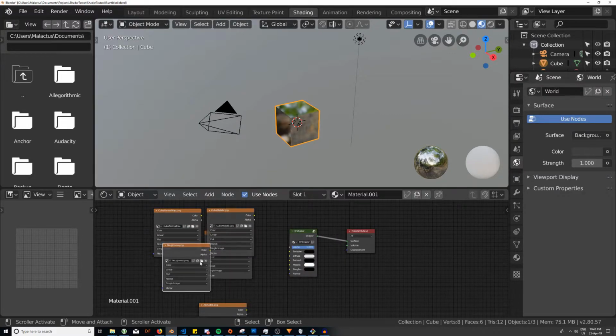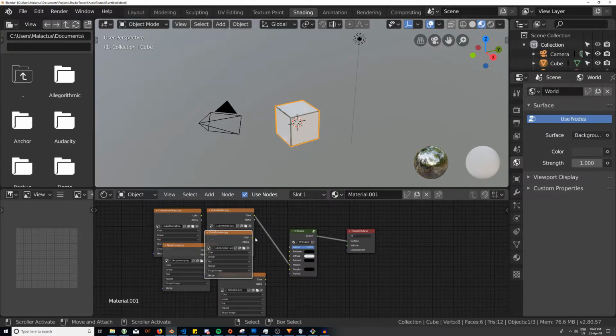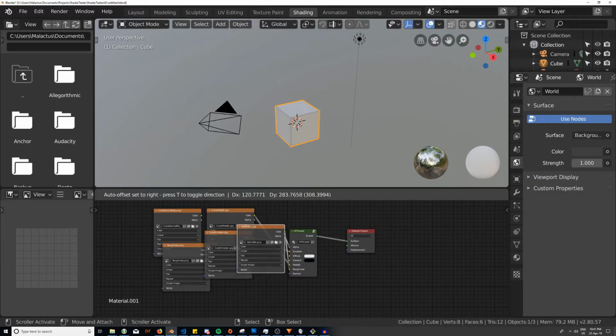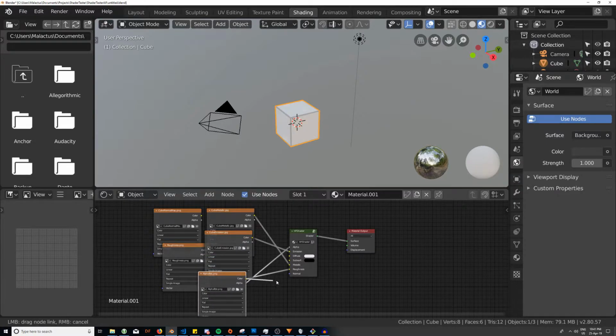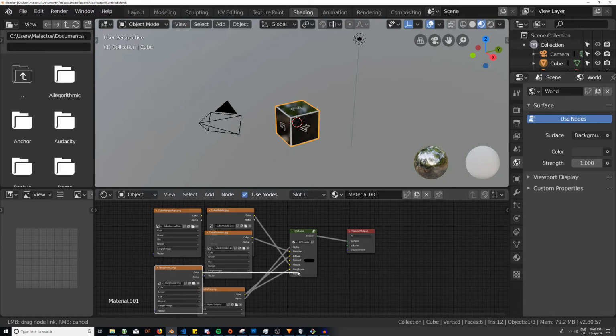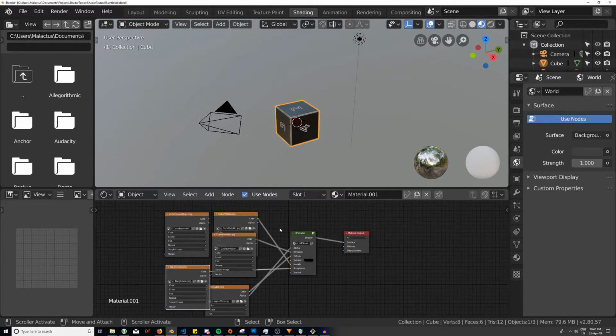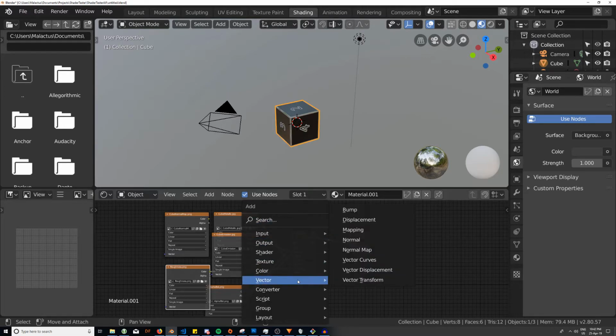To bind them, we are going to connect each texture's sockets to the other sockets. By default in High Fidelity, if you have a diffuse texture, the alpha channel will always be used as a transparency on the model. You will also need a normal map node in front of the normal socket.